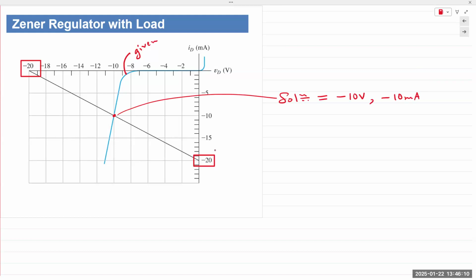If you think back to earlier in this chapter, we performed load line analysis of the regular diode in forward bias. Everything was positive because we were in the first quadrant. Positive voltage, positive current. Now it's negative voltage, negative current. Just reverse bias. That's all it means. So the load line analysis doesn't change. That remains the same for all devices.